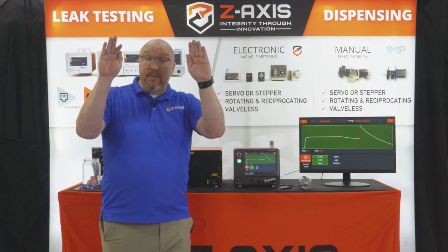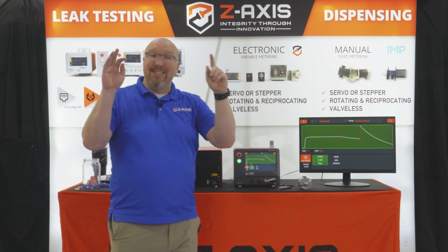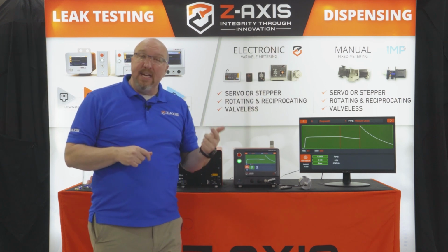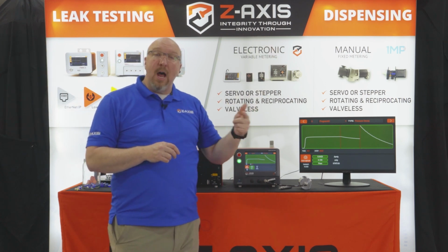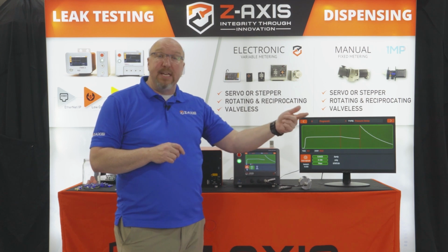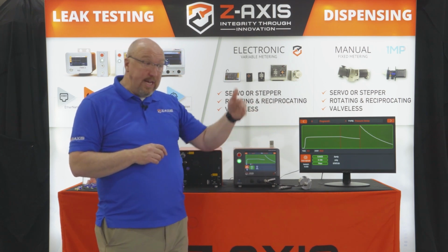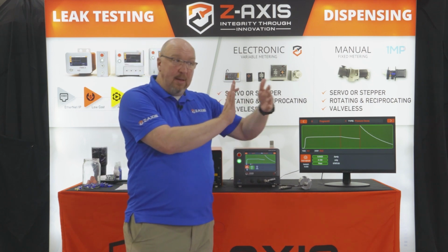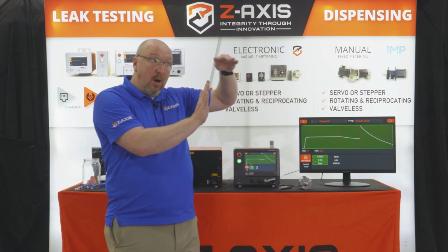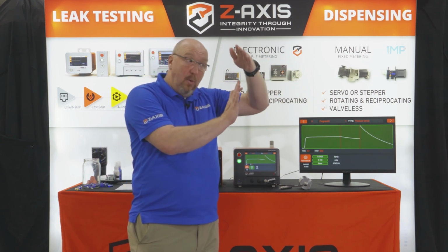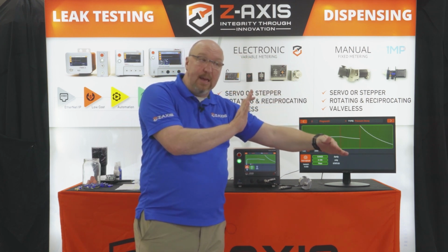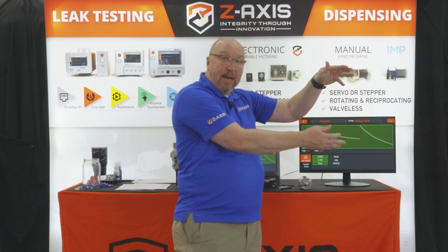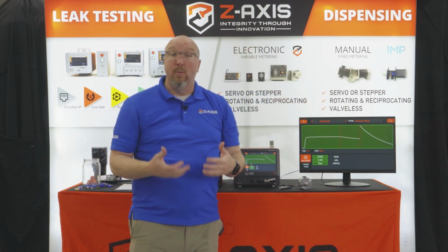Once I get that sufficiently shrunk down, I can now adjust the test step time to start to separate the values. Because the idea is, a good part is not going to decay as much or will stop decaying, where a part with an actual leak will continue to decay over time. So if we took the test step time and stretched it out, a good part's decay would level off and stop, where a leaking part would continue to decay more and more. So the further out we go, the further those two values separate. And when they get enough separation, we can stop there.